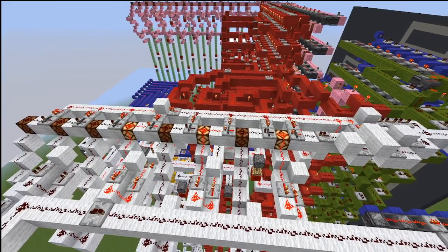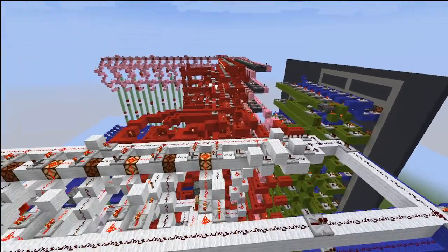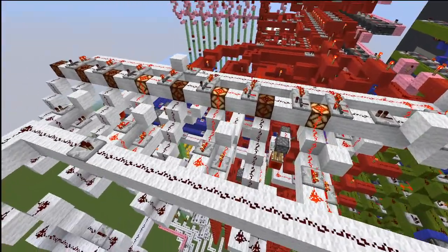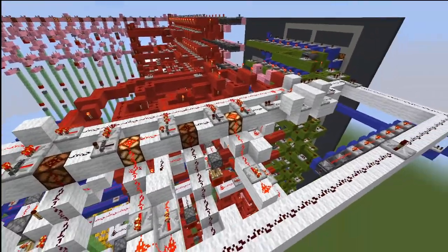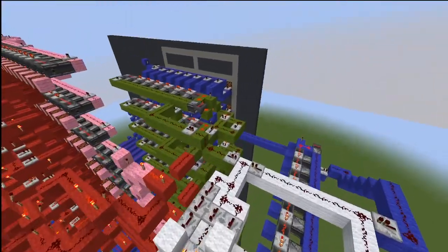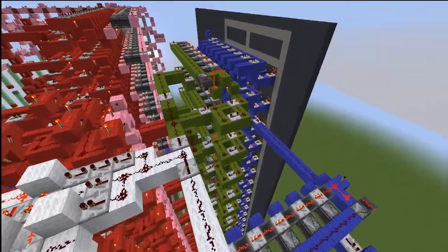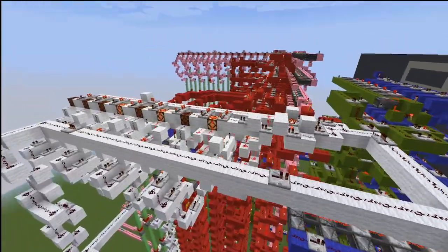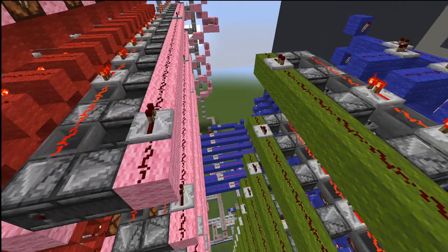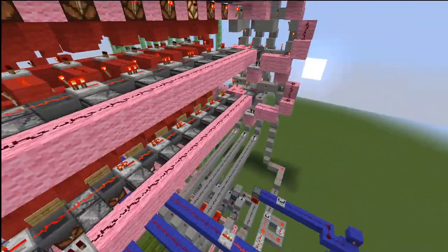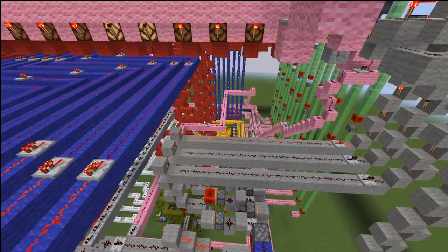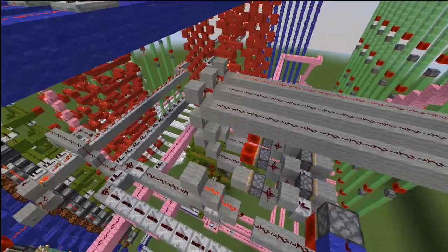And so now it's going to update the instruction register, which I already showed. And then after that, it's going to increment the program counter. And then it's going to read from memory address 5. You can see 4 plus 1 is 5. So it's going to do memory address register location 5 from prom and send that up to the data bus. I'll actually check where the program is right about now. So it just incremented the program counter. So it's going to actually update that on this next clock pulse when that comes in.